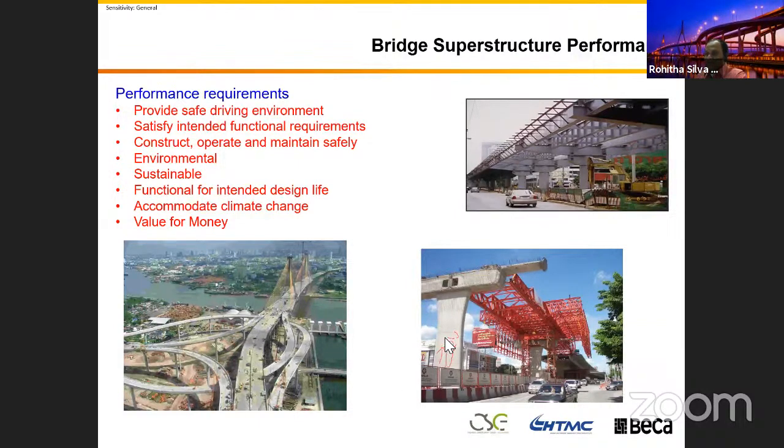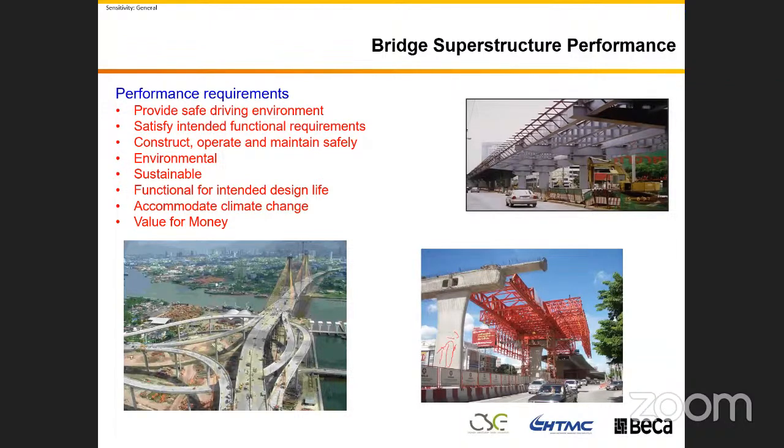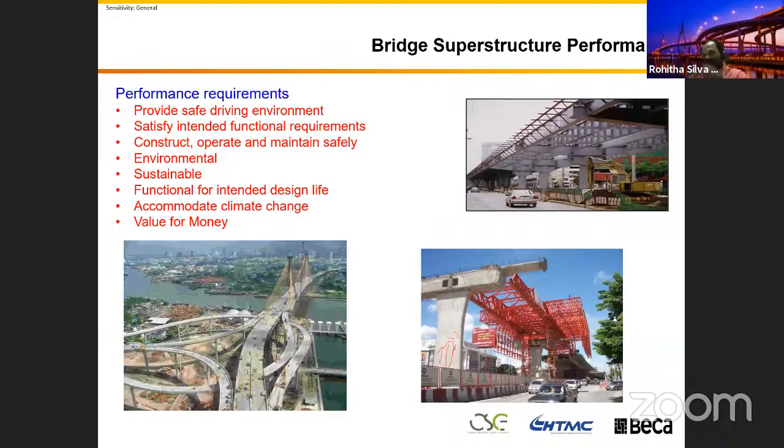I think we considered only that footing when we cast it, which is 21 meters wide and 25 by 4.15. I think we used stage concrete, but in this kind of construction we never worried about the heat of hydration. I think it had sufficient reinforcement plus those days. We didn't pay much attention, especially in Bangkok, but in Australia we actually do heat of hydration analysis plus we come up with a special mix design.